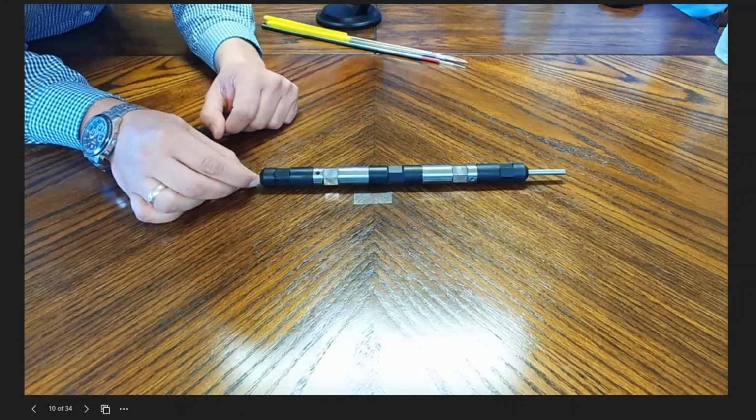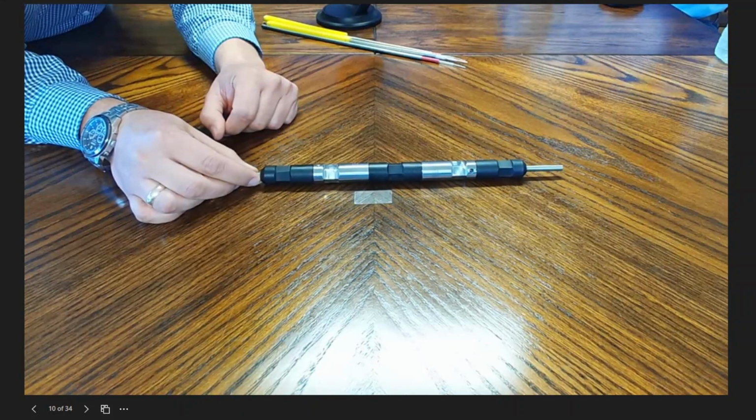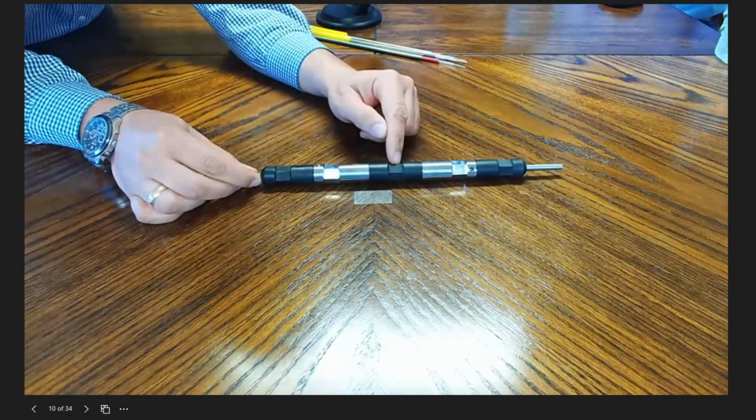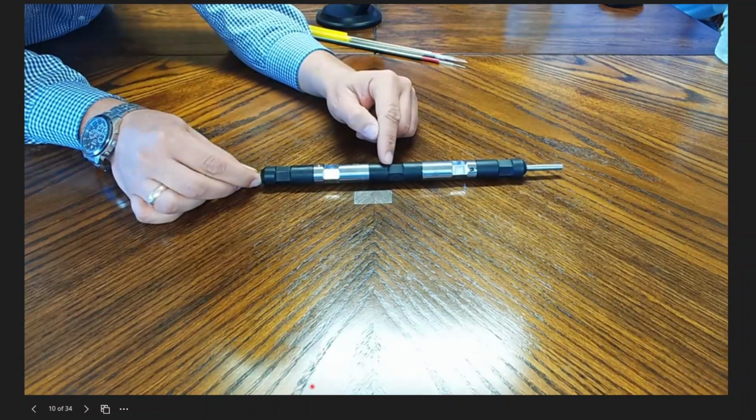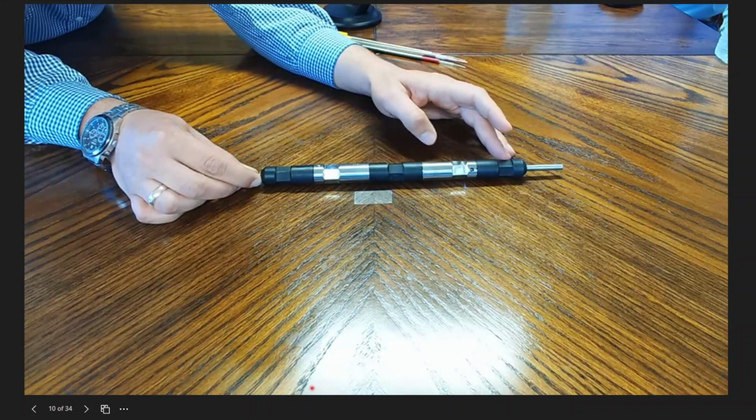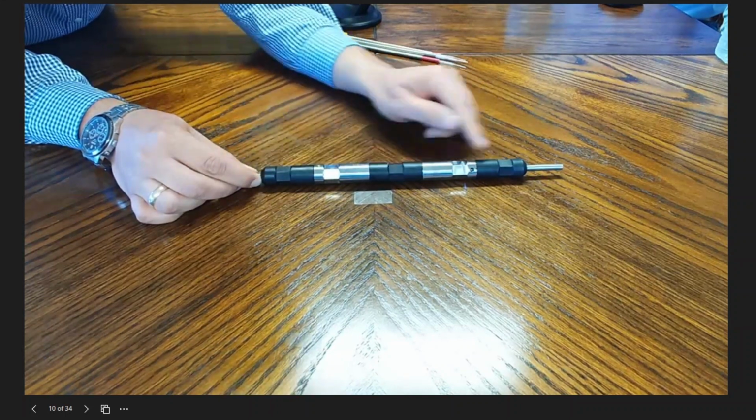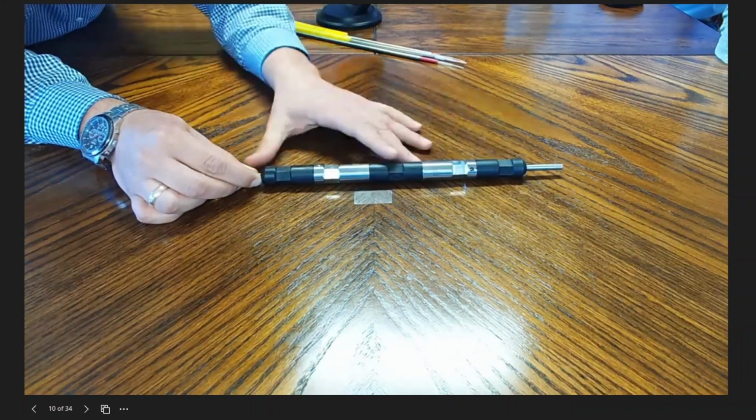Okay. And so that connects two damaged pieces of TEC cable. If they're damaged on the rig floor, you cut that bad piece out and then you can reconnect it using the splice. Correct. You electrically connect the conductor here, and you reestablish the armor integrity with these mechanical parts.